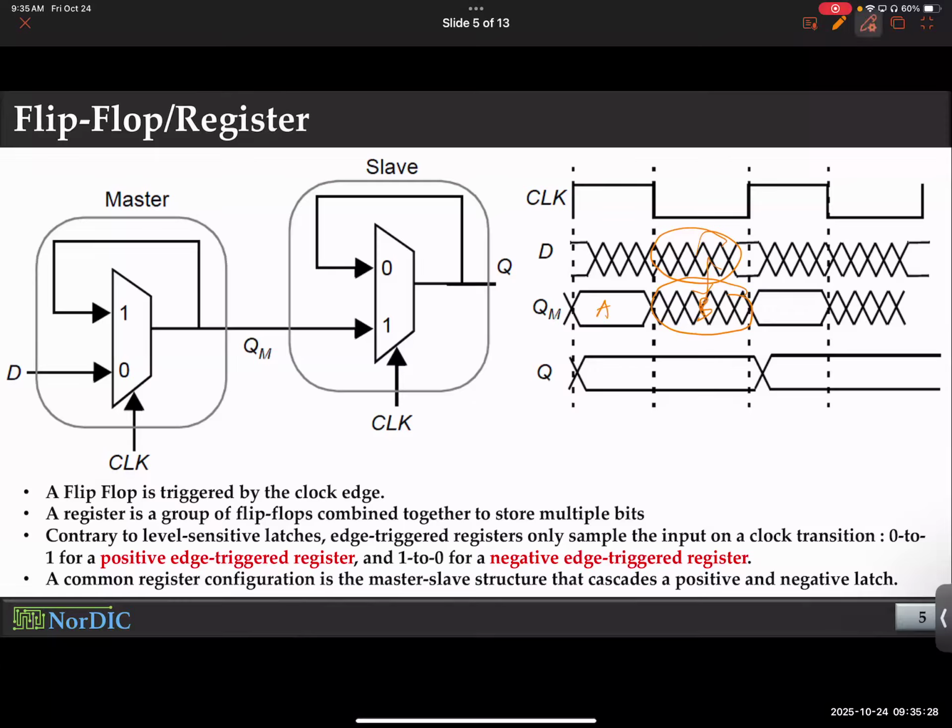Now, take a look at this final output for the second latch. When does it become transparent? Whenever the clock is 1. So that's when it should be transparent. But notice, it is transparent, but do you see any continuous changes here? Or is it always stable? It just has one transition. It reflects that, hey, something changed, and then it stabilizes.